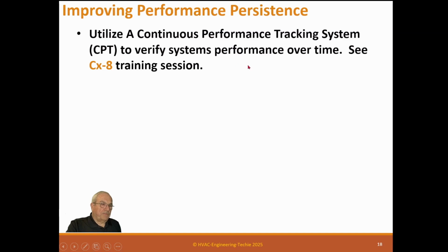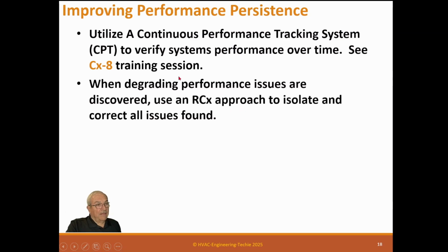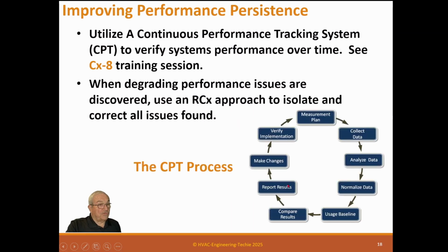So this is that CPT system. I put it here because we talk about it in the others, but I thought it'd be best to put it here. A continuous performance tracking system to verify performance over time. It's actually a Cx-8 training session because we actually also recommend this for new building commissioning, and this details it in action detail of Cx-8. You want to see that, you go to that one. But when degrading performance issues are discovered, use an RCx approach to isolate and correct all issues found.